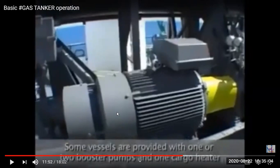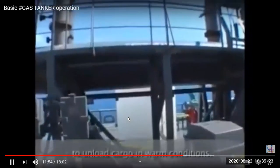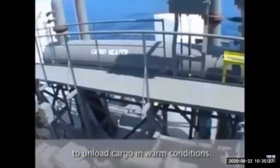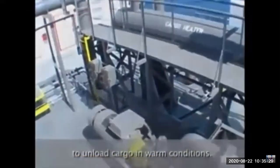Then cargo heaters are there. Suppose the cargo is at -45, and the shore people need the cargo at -42, so we need to heat the cargo a little bit, and that's the time we will use the cargo heaters. So if we want to discharge at a little bit higher temperature, we need cargo heaters.